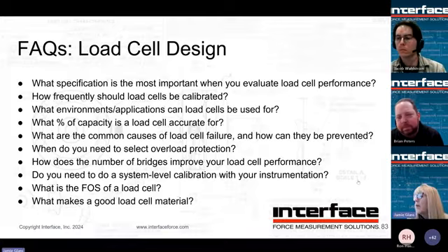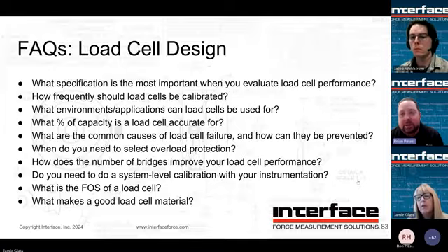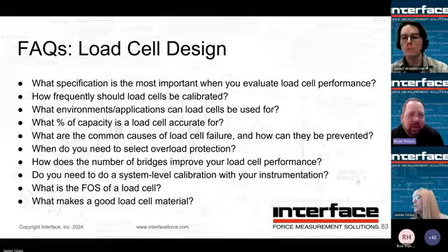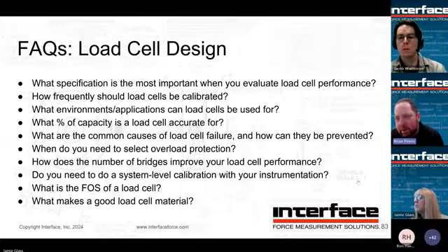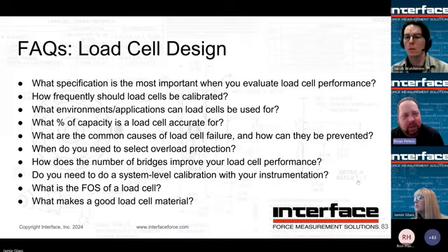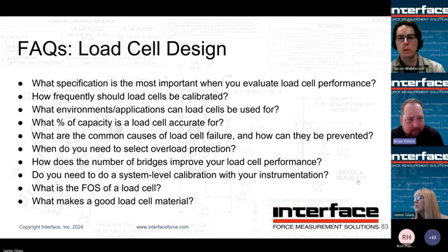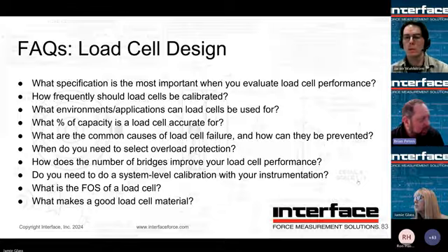Another question is, how do you overcome crosstalk for multi-channel load cells? Good question. You try to optimize through the flexure design. There are going to be limitations, of course, and it comes down to which is your primary axis of measurement. If you're talking an axial-torsional cell, for example, and your axial load is much more important, then we would want to go with one of our 1216 models, which starts as an LP axial load cell and adds torsional bridges.